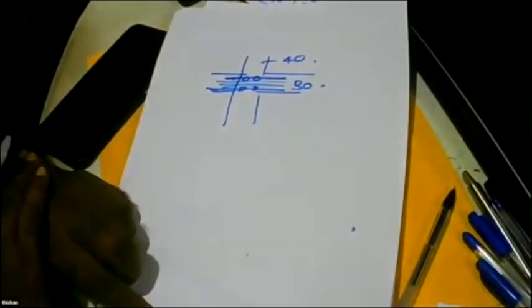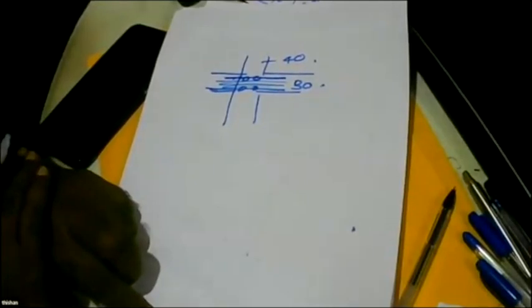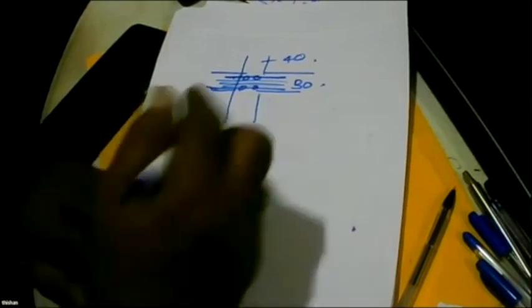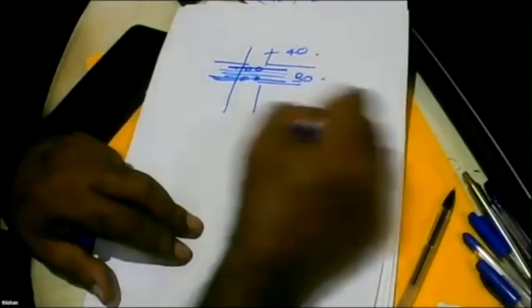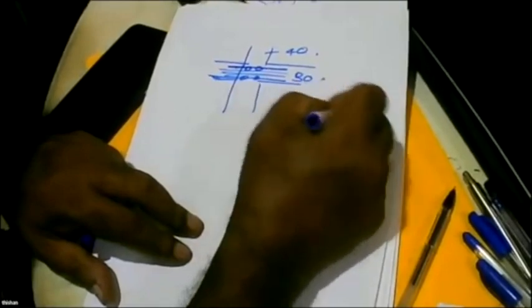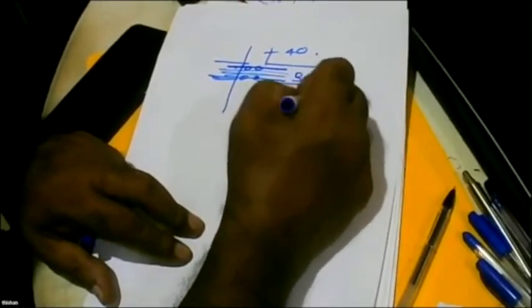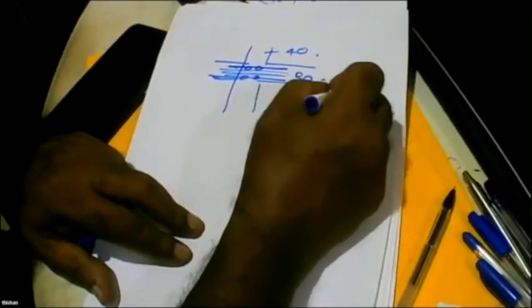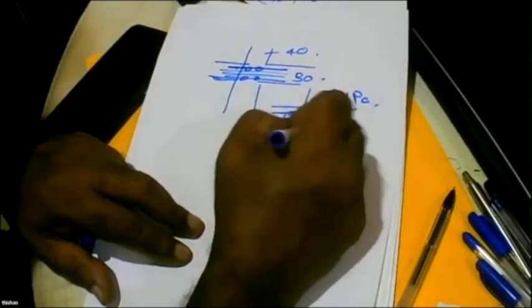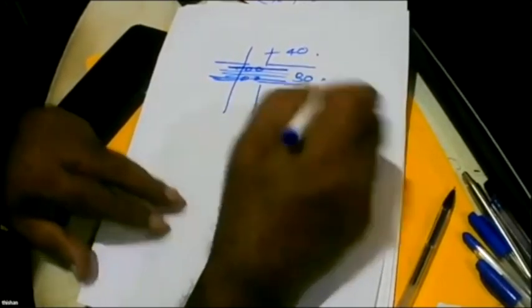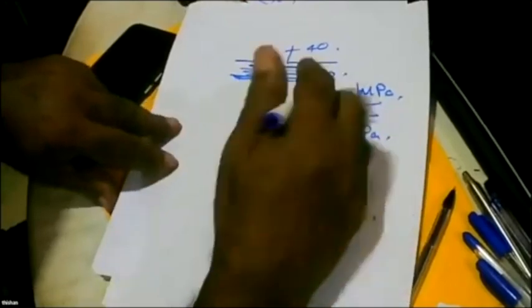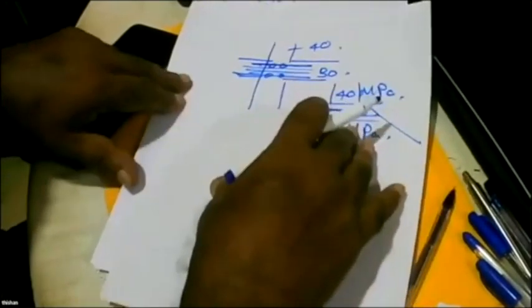So because of this huge amount of reinforcement, there's a huge amount of confinement. So even 30 megapascal concrete can easily transfer the load, that is the stress that is induced in a 40 megapascal concrete. So that's the reason. So even in a raft foundation, you have a lot of reinforcement in these directions. So you have 40 megapascal here. Here you have 30 megapascal. It doesn't matter, because all these reinforcement can do the dispersion into the concrete.